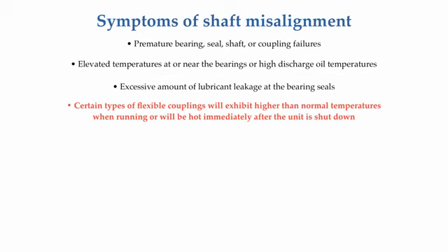They started off by carefully aligning the shafts to near perfect alignment conditions, started the motor up, ran it for 15 minutes, got their new infrared thermal imaging camera, and took a thermal image of the coupling. They then shut the motor down and let it cool back down to ambient temperature. They then loosened all 4 of the motor bolts, installed 10 mils of shim stock under all 4 feet, and tightened the bolts back down.